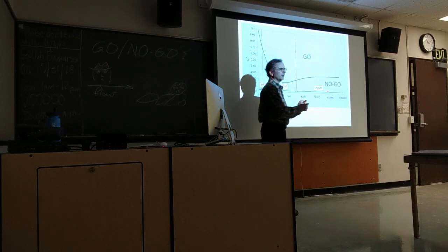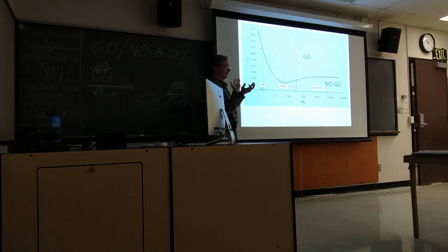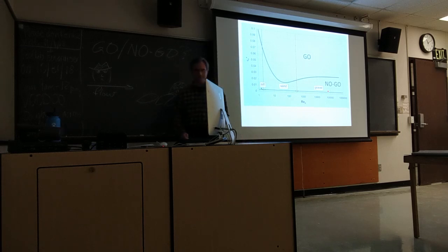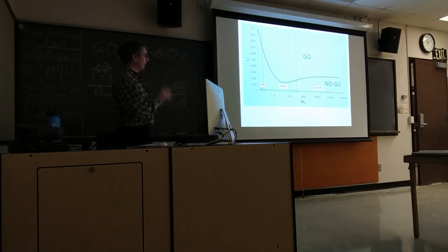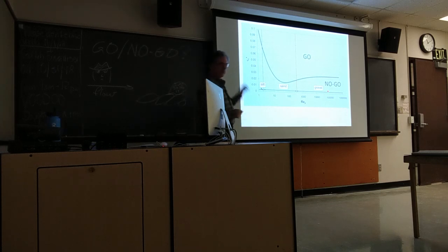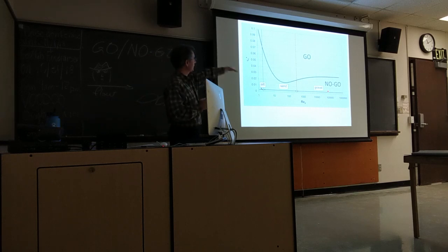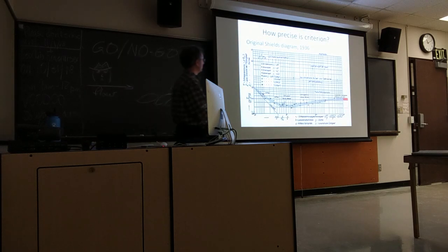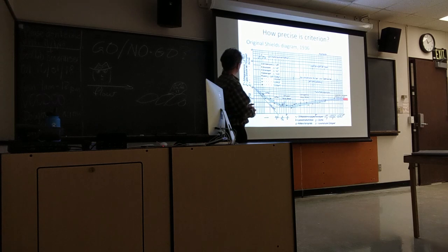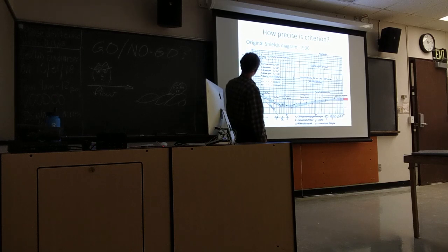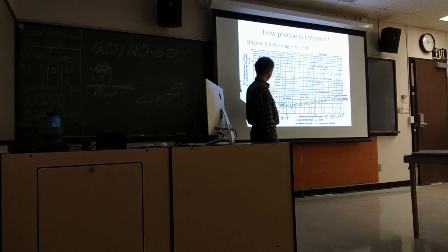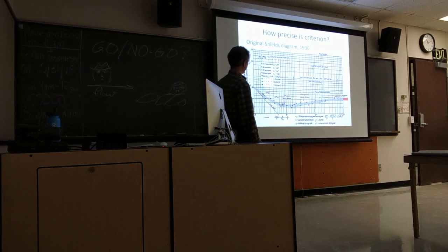Now, so far, this is going to be a bit perhaps mysterious because I haven't yet defined exactly how we get either of these dimensionless numbers. I'll get there. I just want to show you what we're dealing with first. So this is a functional fit that somebody's made to data. This was Shield's original curve or diagram. And boy, if you're really spiffy, you can decipher what this actually says here, because it does give us the formula for the Shield's number and his particle or roughness Reynolds number.